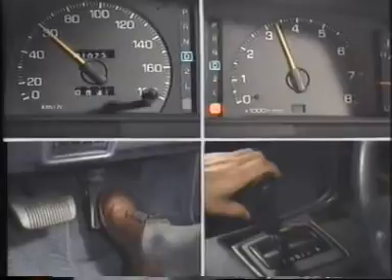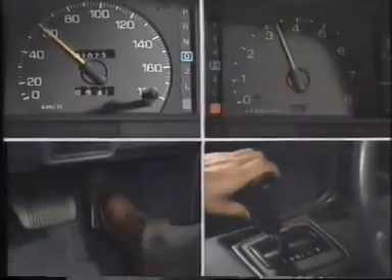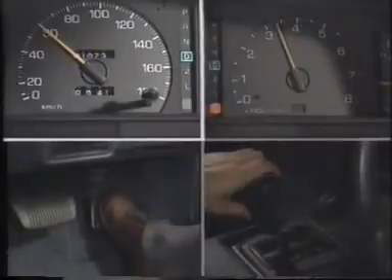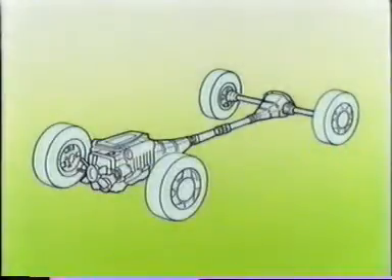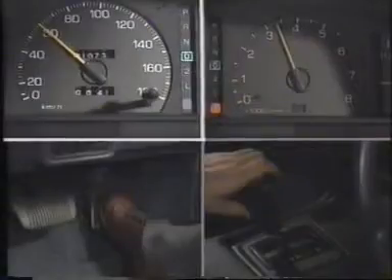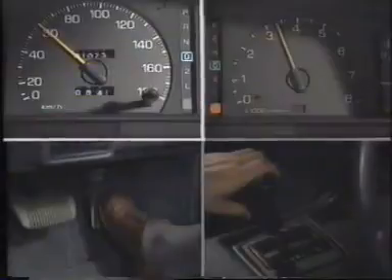The test results indicate that the engine load and the engine speed are not related to the problem. The shift lever position is also unrelated to the problem. You can now conclude that the vibration is not caused by the engine or the transmission. So we need to look for some other factors.